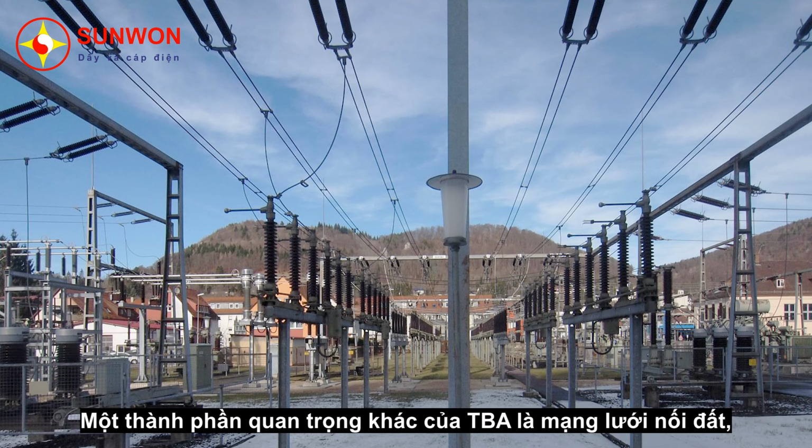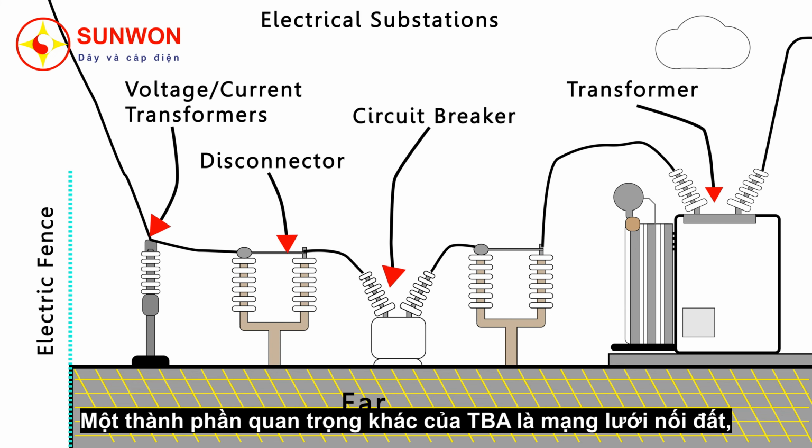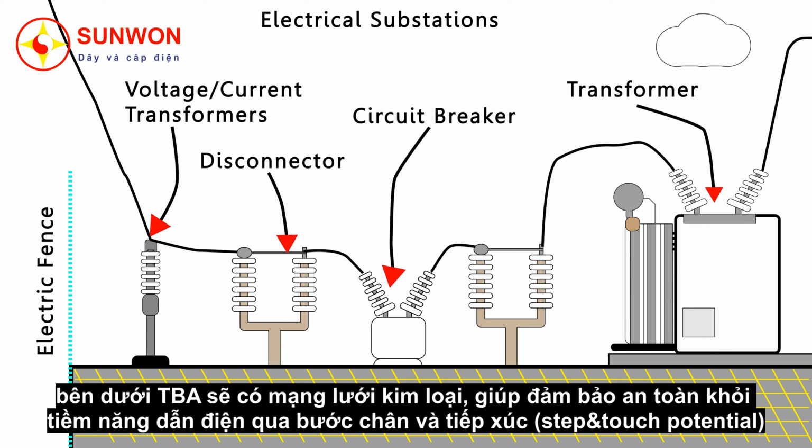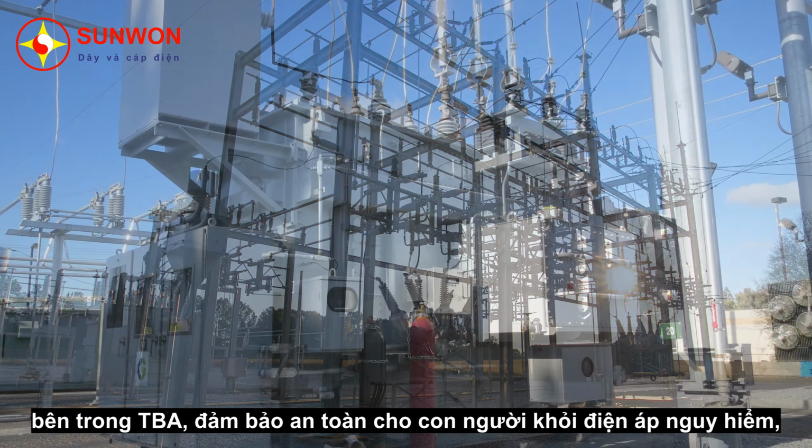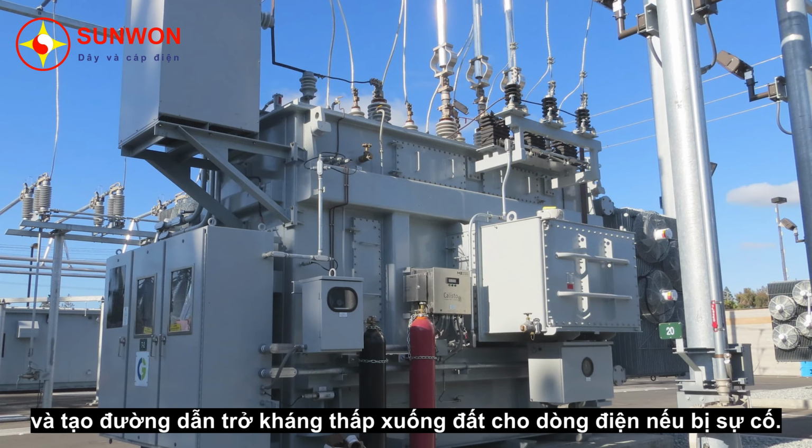Another important aspect of the substation is the earthing grid. Underneath the substation, you have a metallic grid, and that helps maintain safe step and touch voltages within the substation to protect personnel from dangerous voltages and to also provide a low impedance path to ground if there's a fault.